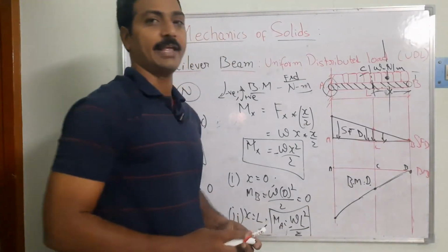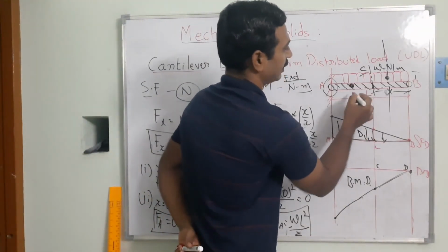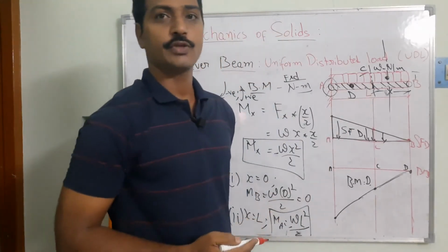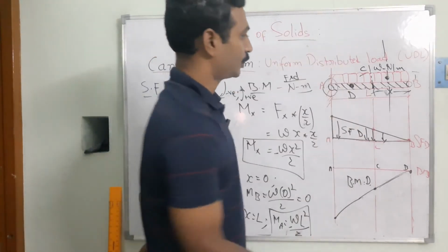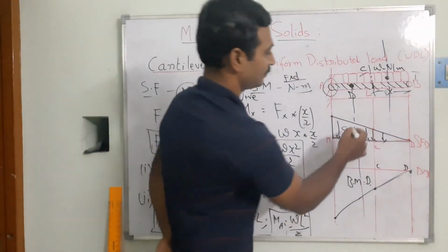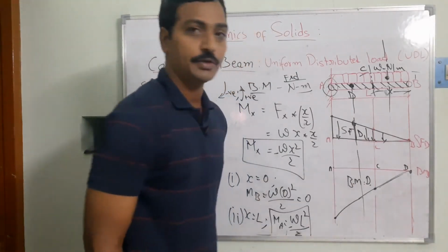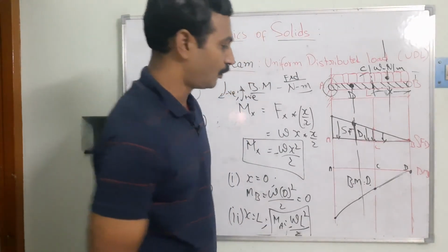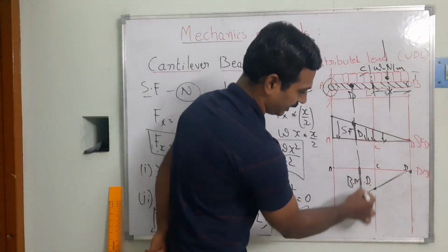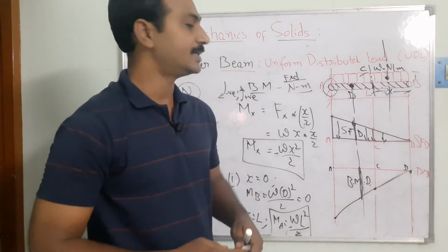Now as for the scale, if I want to find out the bending moment and the shear force at the point D, suppose. So what I am going to do, I am going to be taking the projection of this line which is passing through these points. So whenever this point is coming, this height is going to be the magnitude that is representing your shear force, and this height is representing the magnitude, and then we can find out the bending moments.